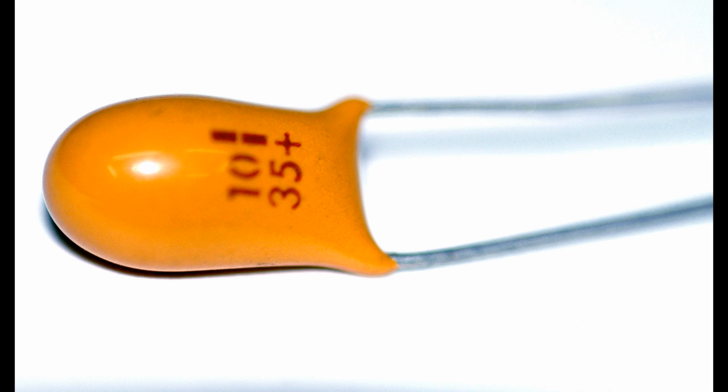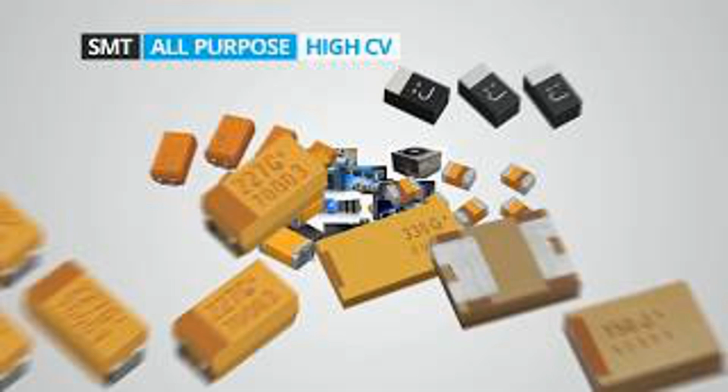4. Polarization. Tantalum capacitors are polarized, meaning the voltage must be applied in the correct direction. If reversed, the tantalum pentoxide layer can break down, causing the capacitor to fail (short circuit). This is different from non-polarized capacitors like ceramic capacitors, which can handle voltage in either direction.